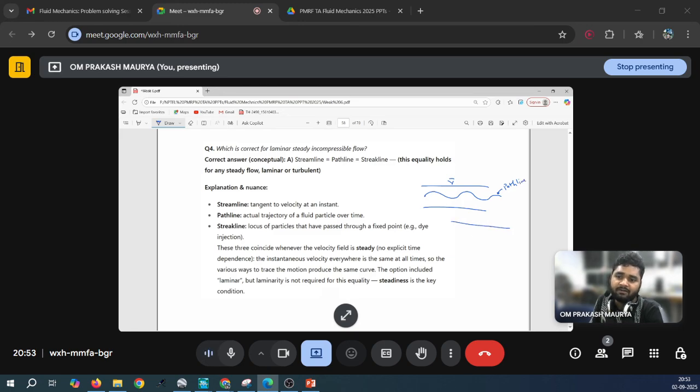You have the flow domain and at a particular time you have just taken a picture and you are analyzing. So what you will see is a lot of fluid particles like that. That is the combination of many fluid particles. Here you are only looking at one particle, but at an instant of time you have millions of fluid particles, and the flow is like that. When you draw a tangent, you will get the velocity of the particle. So this is your streamline definition.